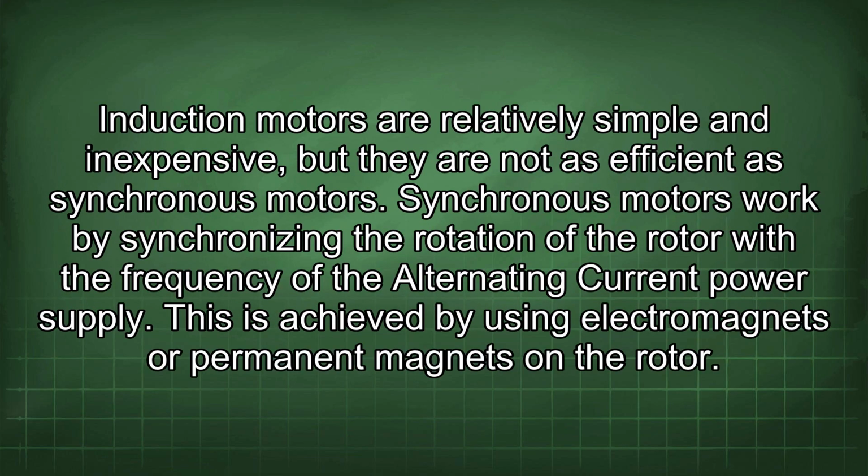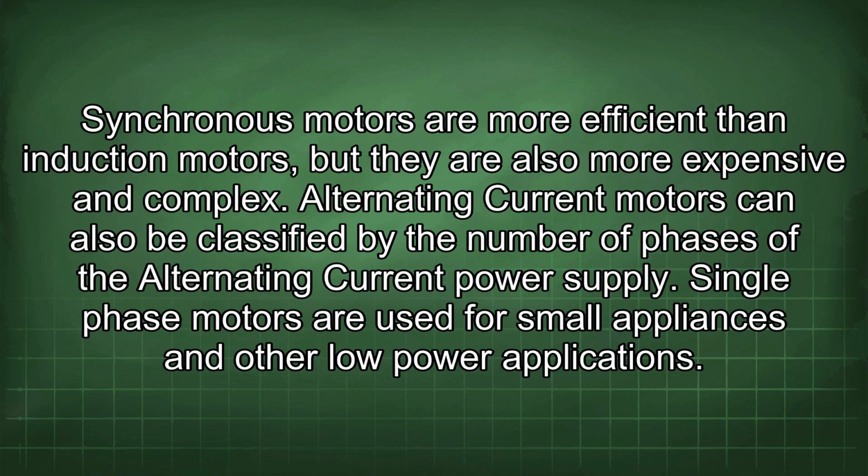Induction motors are relatively simple and inexpensive, but they are not as efficient as synchronous motors. Synchronous motors work by synchronizing the rotation of the rotor with the frequency of the alternating current power supply. This is achieved by using electromagnets or permanent magnets on the rotor. Synchronous motors are more efficient than induction motors, but they are also more expensive and complex.